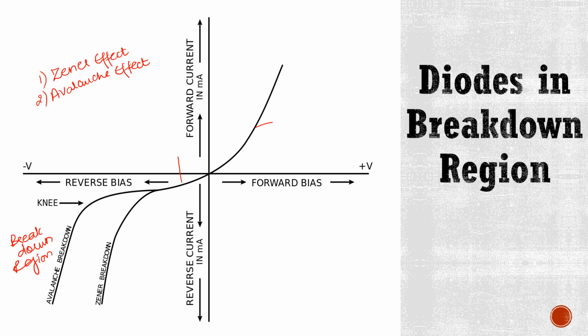It means here this Zener breakdown is occurring at -5 volts, whereas breakdowns occurring at voltages more negative than -5 volts are caused by the avalanche effect. In general, this avalanche breakdown usually occurs at -7 volts.